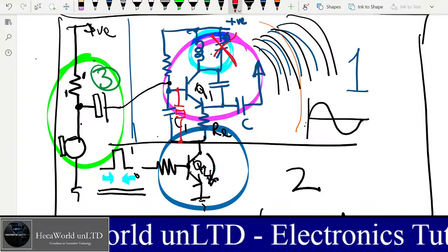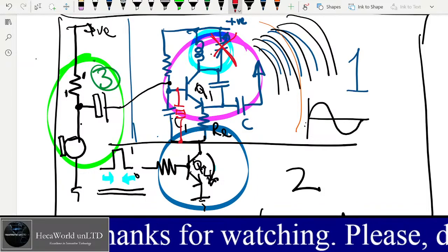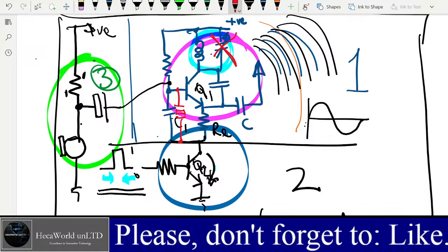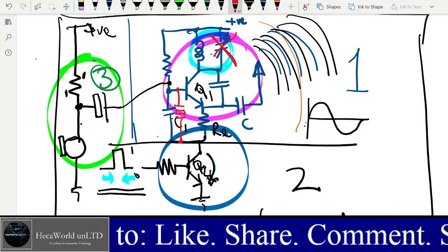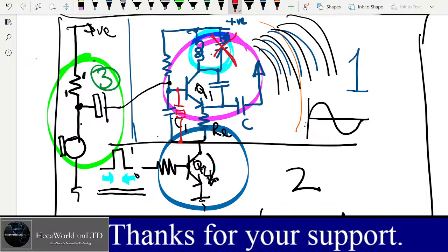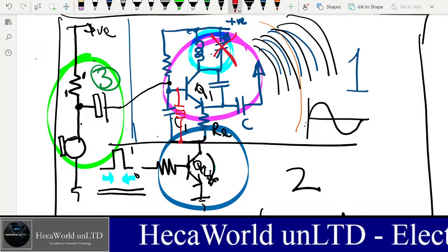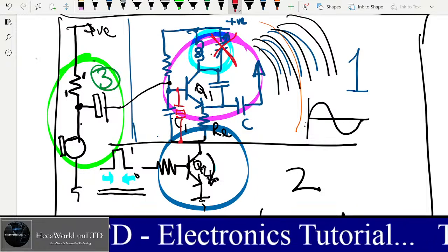So if you want to have a fixed frequency for remote operations, you want a fixed frequency transmitter, or you have to have a fixed voltage transmitter. Make sure that voltage is stable, and the proximity of any object to the antenna or to the circuit is the same all the time, because if it changes, it could affect the waveform or the wave pattern.